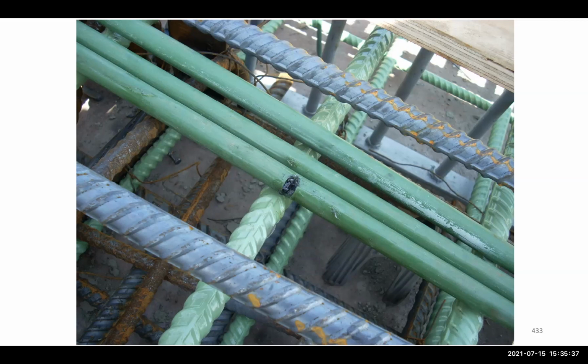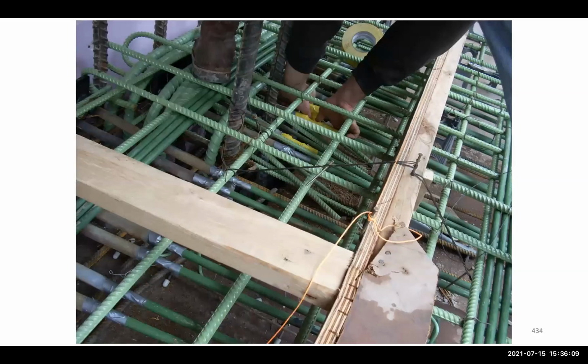7-wire strand. So if one wire is cut or two wires are cut, what do we do? Okay, so we don't have to replace it maybe, but we have to apply the force that's required. So maybe we apply more force to the remaining 5 to take that force that is required. Instead of being applied to 7, they will be applied to 5. So we increase the force so the 5 can have the same force.